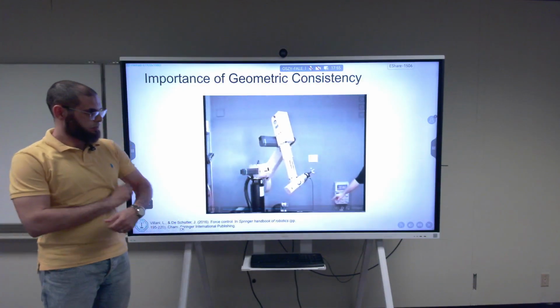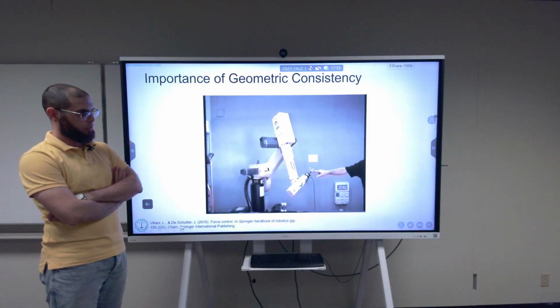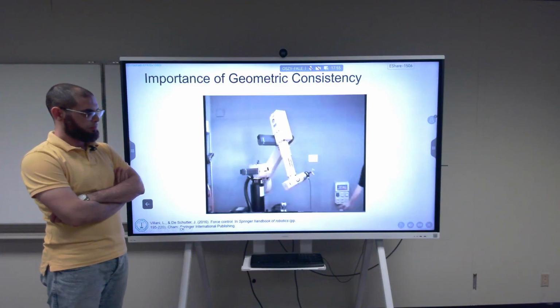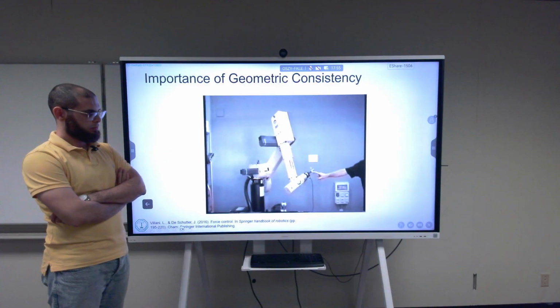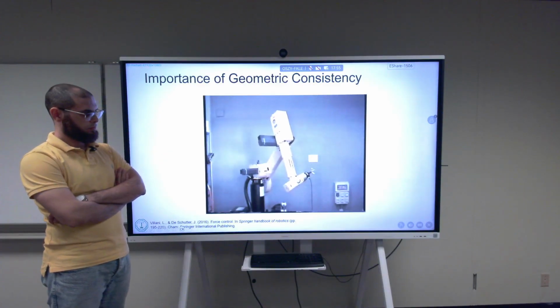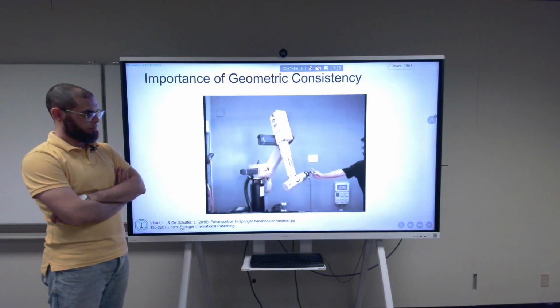According to the classical operational space approach, the orientation displacement is given by the difference between the actual and the desired set of Euler angles. When an external moment is applied about one of the tool axes, rotations are induced also about the other two axes.